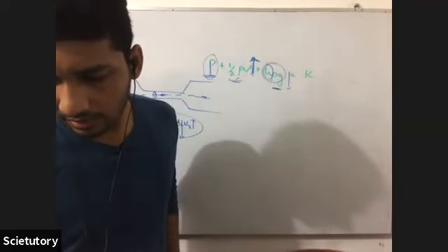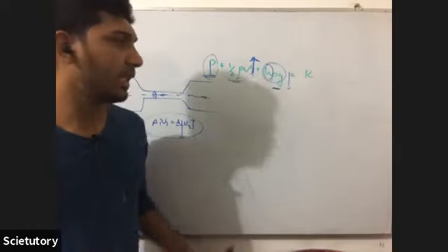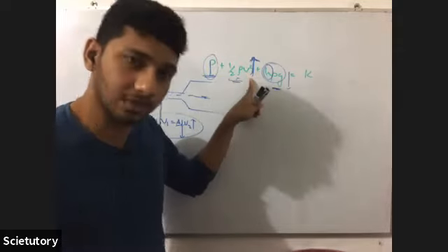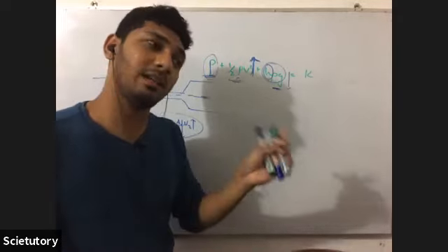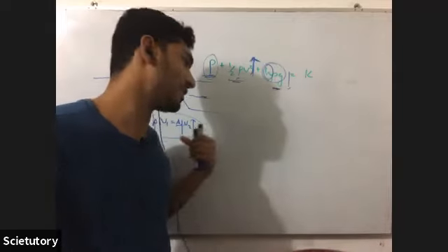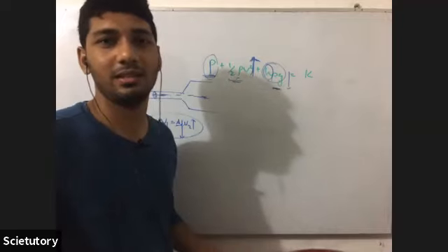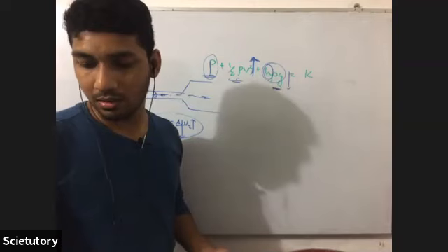That is again the continuity equation. If they tell about the increase in the velocity, that is explained by Bernoulli. But if they talk about the reduction in the cross-section, that is explained by the continuity equation. So you should carefully think here. So B is also wrong.